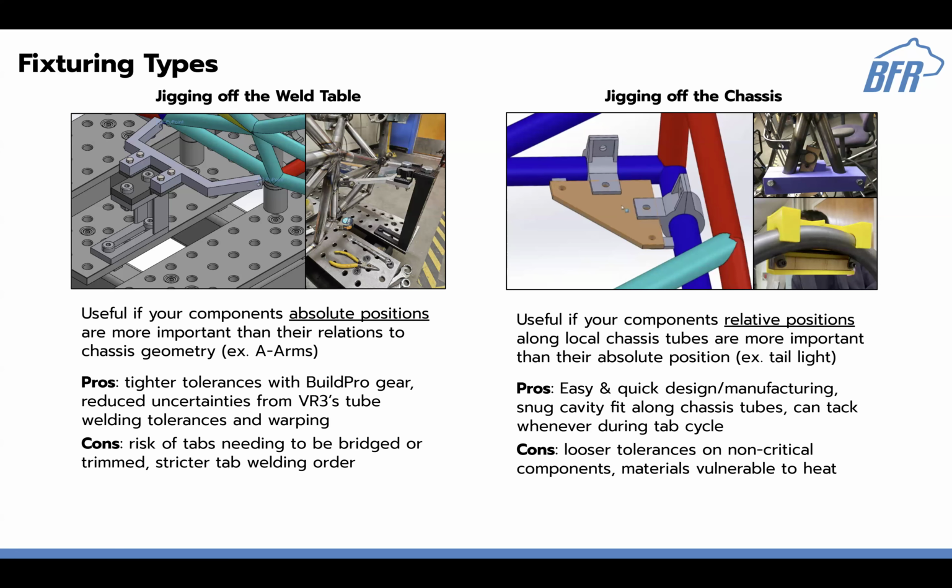So you might have a little bit of a gap that you need to bridge with welds. Or you might need to cut down the tab if it's running into it. You're also limited more by hardware since we're using a lot of these tabling components. We have to be strategic about what order we're welding all the tabs in, and this is the main constraint for our timeline.